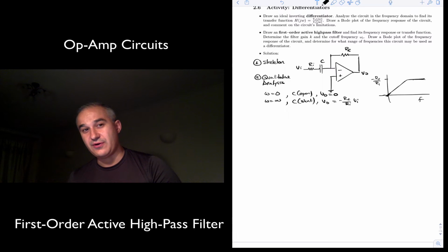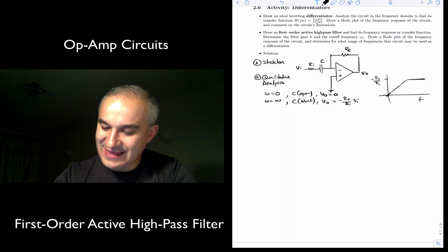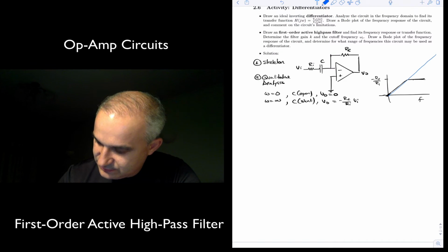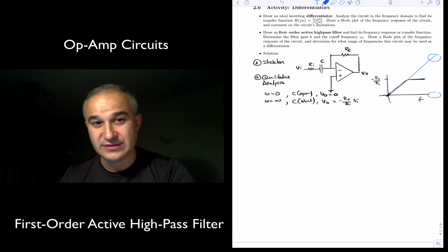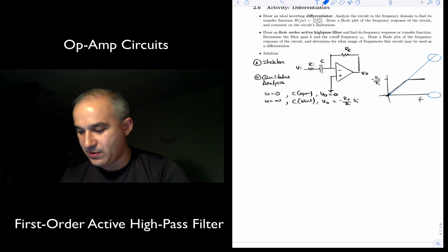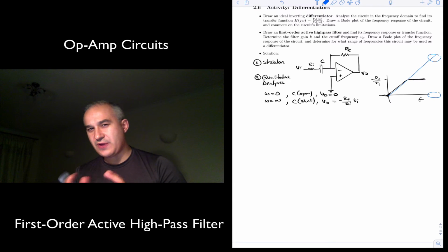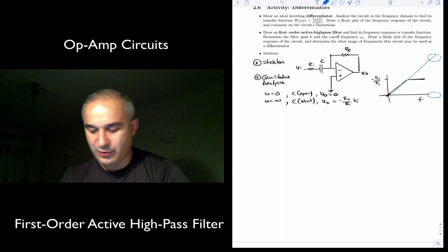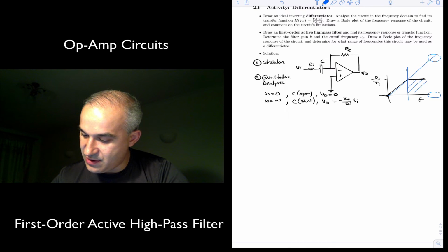We are dealing here with a high-pass filter. Now, if you recall, the ideal differentiator, the frequency response, looked like this. And that's where we had high amplification at high frequencies, where we have noise, and that created a problem. And so, how is a first-order active filter different from a differentiator? And over what region does it behave the same? Clearly, not in this region here.